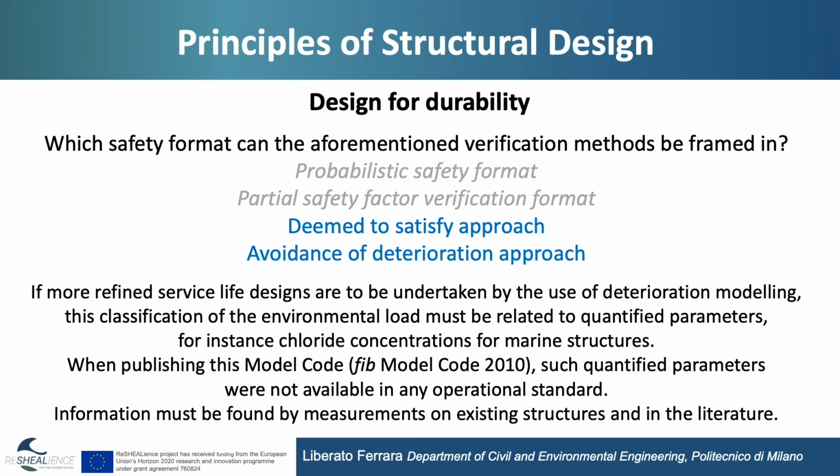As a matter of fact, in designing for durability, we have the possibility of framing our approach into 4 different levels. And if we review them from bottom to the top, they are the followings: avoidance-of-deterioration, deemed to satisfy approach, partial safety factor verification format, and probabilistic safety format. As a matter of fact, the current approaches which we find in the codes are based on avoidance-of-deterioration approach or deemed to satisfy approach.